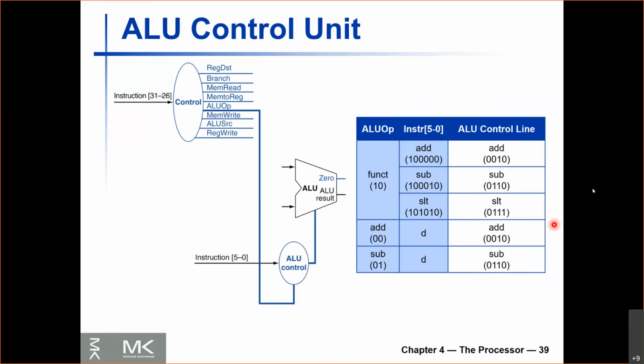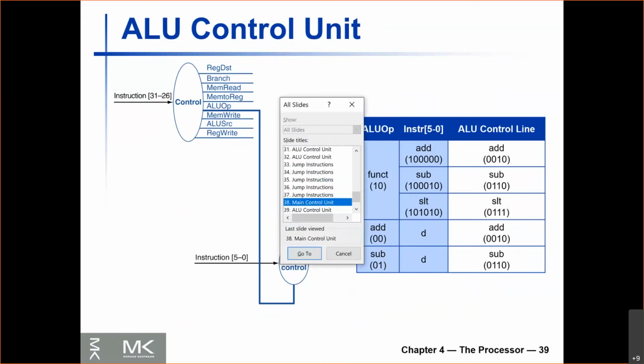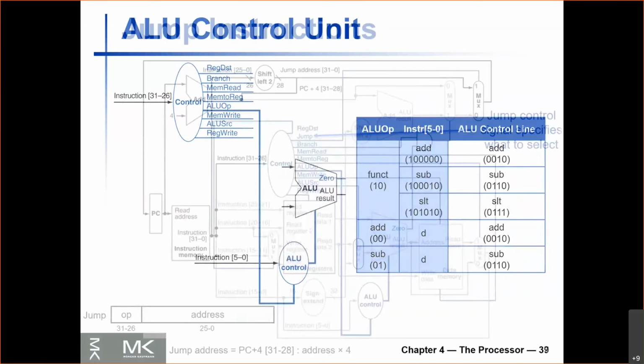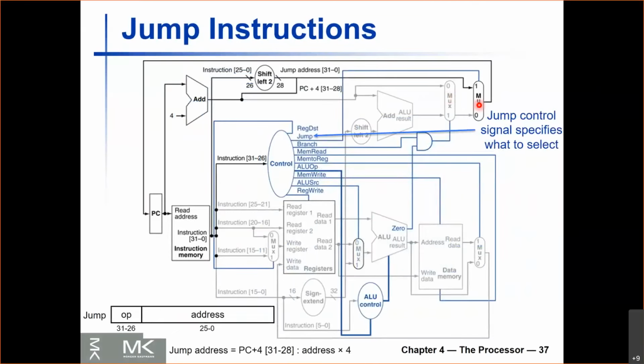Okay, so someone's asking, why do we need a new mux for the jump instruction? So we can have a 3-input mux, or we can have two 2-input muxes. It's here just for the sake of explanation and showing you how we have the jump signal that controls this selection, and we have the branch signal and the 0 that controls this selection. We've separated them into 2 separate muxes. You can also think of them as 1 mux that uses the combination of all these other control signals.